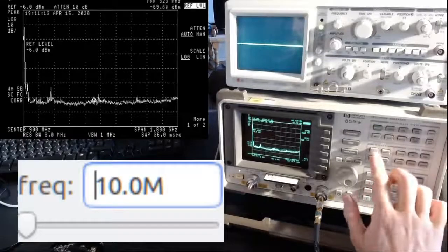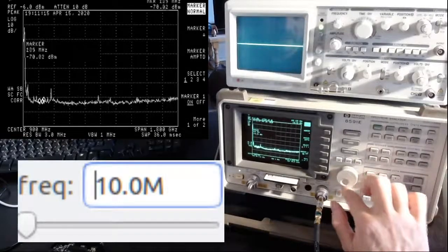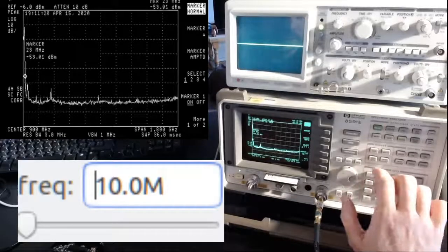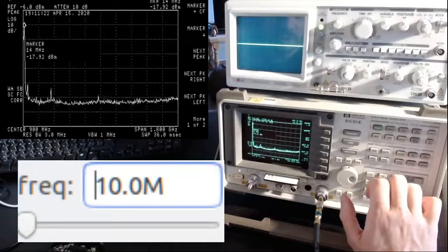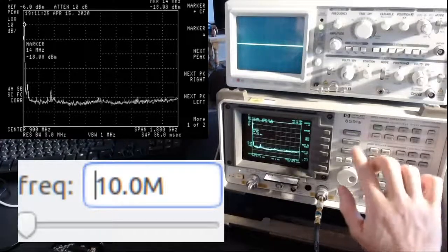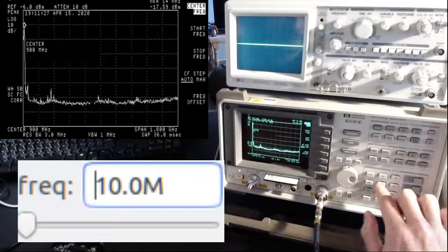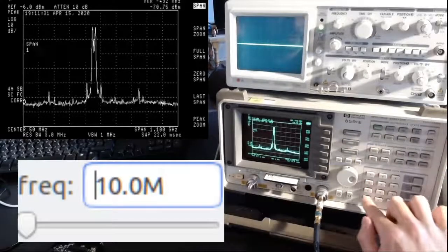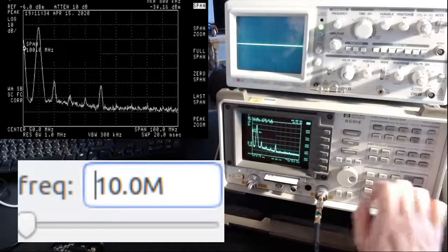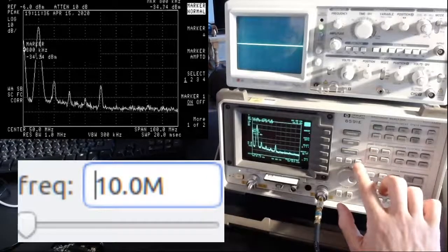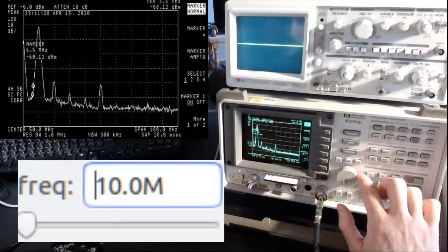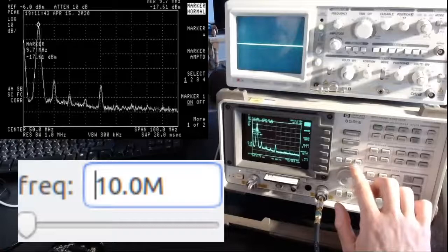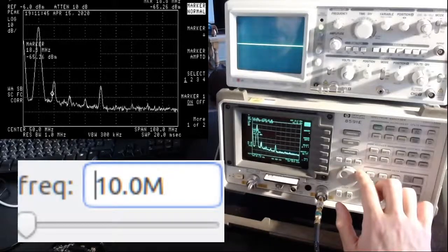Anyway, it has to be said that the signal here at 10 megahertz is, so let me find it, the peak with the peak search function. So actually let me zoom in a little. So frequency, let's put it at 50 megahertz and a span of 100 megahertz. So with the marker we can see that we have our signal here at 10 megahertz. Perfect.